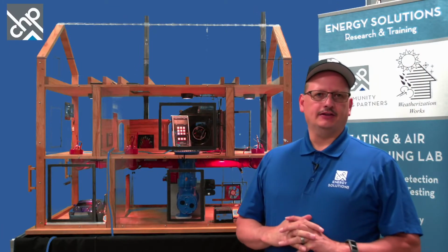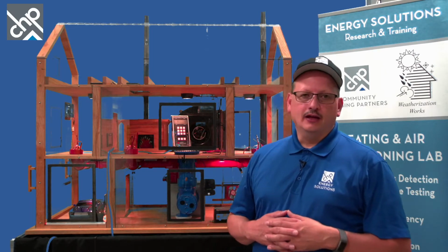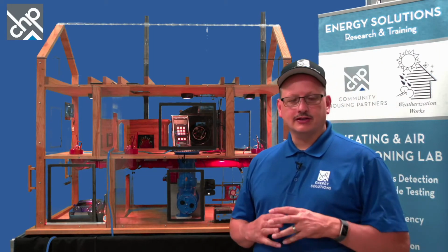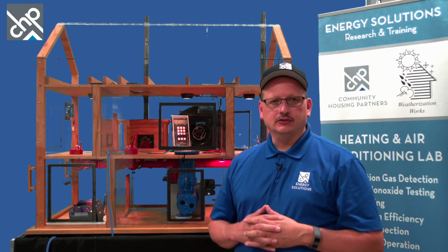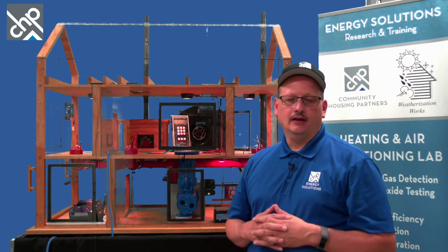All right. We finished doing the duct leakage and the kitchen exhaust. We're going to do some door closure things here, and like I said, when you've got a central return, closing doors can really affect the pressure. It's kind of like duct leaks. They're cutting off the airflow from one area to the other, and we'll do some little demonstrations of that, see how it affects the pressures, and maybe talk about some solutions and fixes for that.